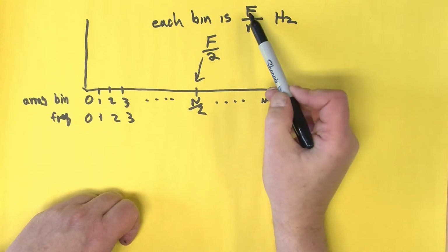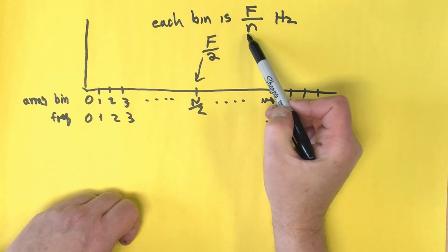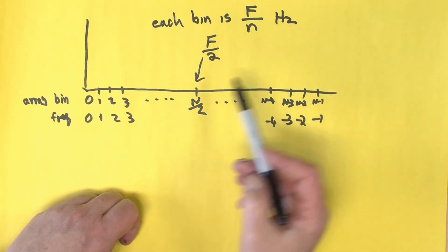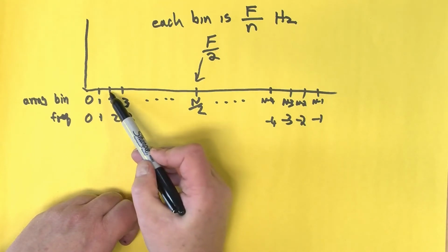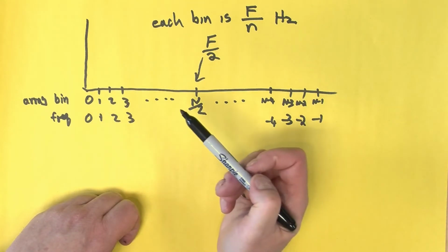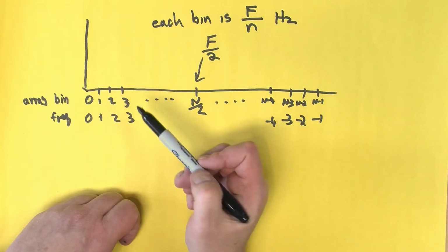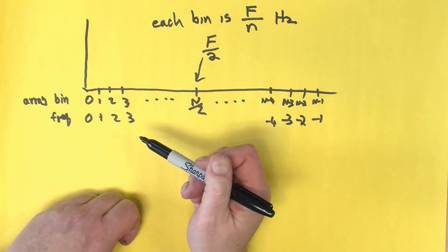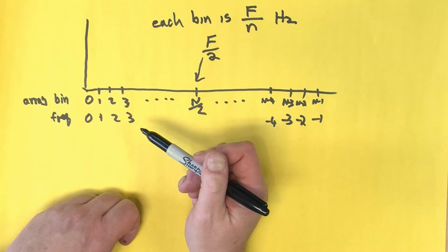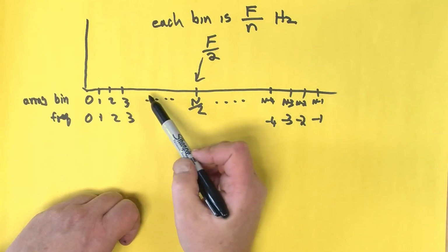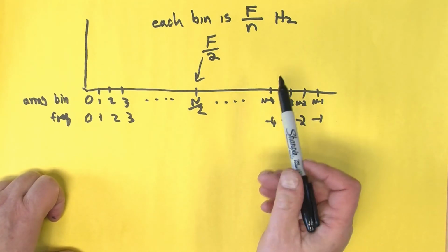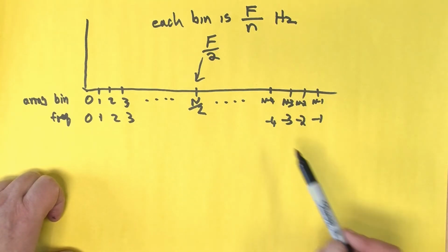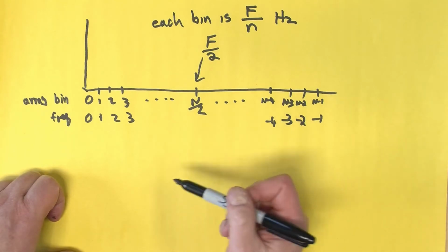So we can choose our sampling frequency and number of samples to determine how many samples we have and how wide each of these frequency bins are. And we would choose that based on what level of detail we want in determining the spectrum. So that's really all there is to it in terms of figuring out frequencies.